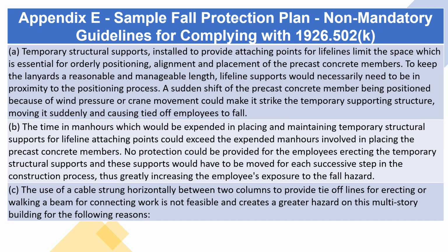A. Temporary structural supports, installed to provide attaching points for lifelines, limit the space which is essential for orderly positioning, alignment and placement of the precast concrete members. To keep the lanyards a reasonable and manageable length, lifeline supports would necessarily need to be in proximity to the positioning process. A sudden shift of the precast concrete member being positioned because of wind pressure or crane movement could make it strike the temporary supporting structure, moving it suddenly and causing tied-off employees to fall.